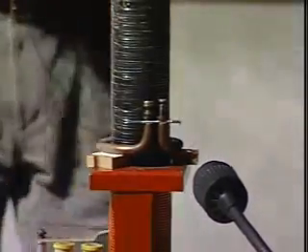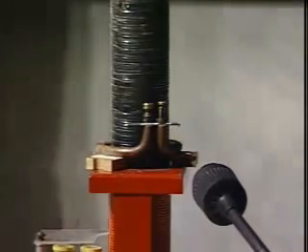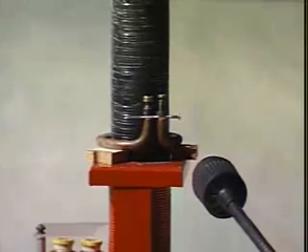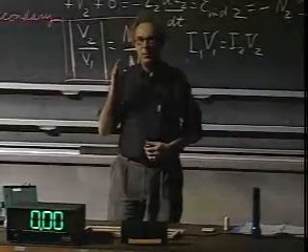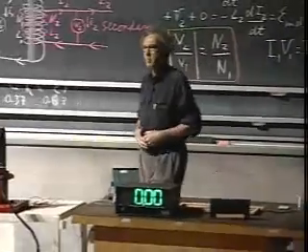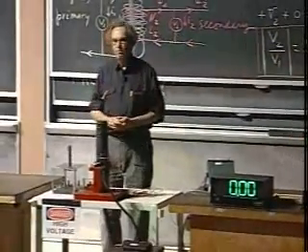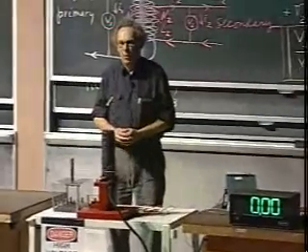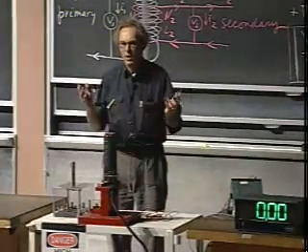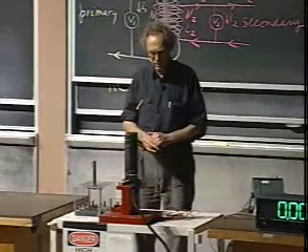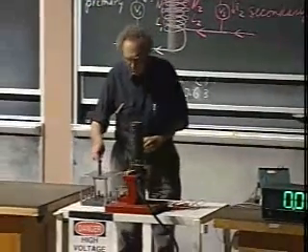And so now if I power the primary, I can't tell you exactly what the current is through the secondary, but it's probably somewhere in the vicinity between 500 and 1000 amperes. It will glow. It may take 1 minute to melt. It may not melt at all. It may take 3 seconds. Unpredictable, because we don't know exactly the resistance of that nail.